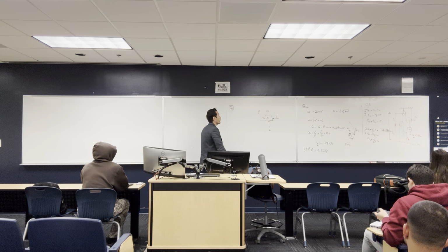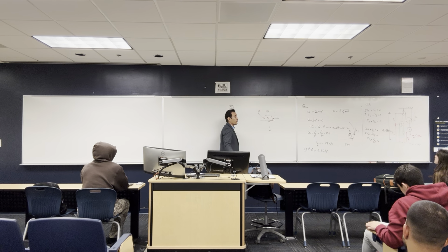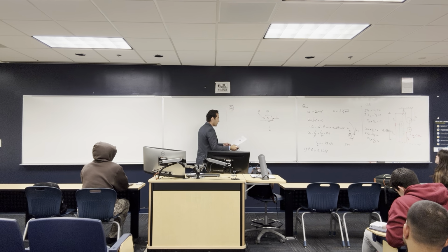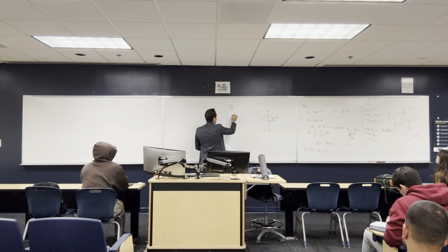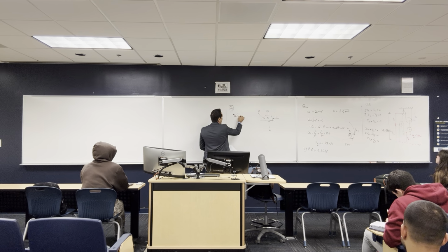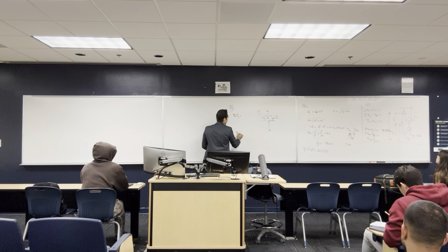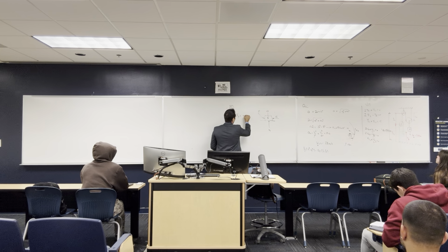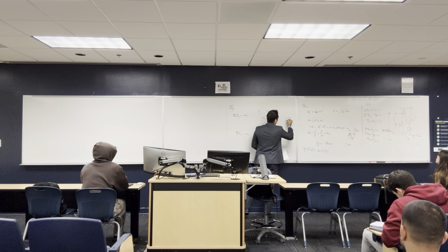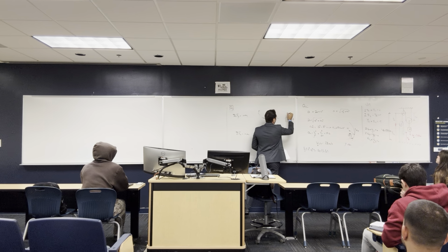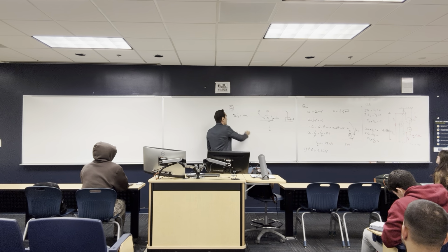What you have to do is analyze all these forces using Newtonian kinematics. Since this is an XY coordinate system, you get the summation of the forces in the Y direction and the summation of the forces in the X direction. This is equal to m a_y, and this is equal to m a_x. If I draw the kinetic diagram, assuming this body is moving that way, this is X and this is Y. I know that the acceleration in the Y direction is 0, so all the forces in the Y direction sum to 0.